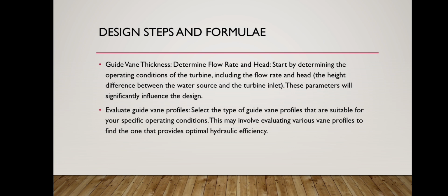Design steps and formulae. Guide vane: in this we are going to see the guide vane thickness. To determine the flow rate and head, we have to start by determining the operating conditions of the turbine, including the flow rate and head, the height difference between the water source and the turbine inlet. These parameters will significantly influence the design.